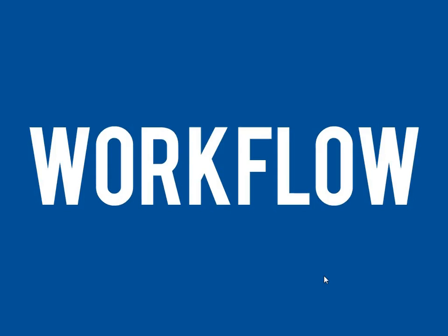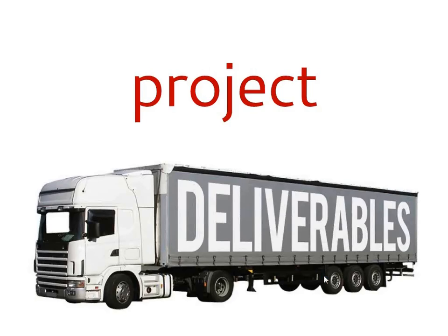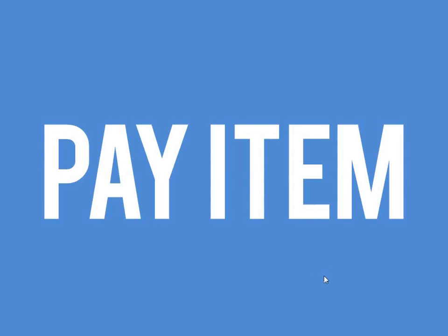Now we're to this final section where we've looked at some of these things. Let's talk about cost estimating workflow. What's the actual process? If we were starting from the ground up, how would we put an estimate together? So we'll use Hard Dollar's HD estimating module for the examples that we show, but the inputs are the same regardless of what you're using. So the first thing we need to do is establish the project deliverables that we're talking about. This may vary a little bit depending on what the contract type is.